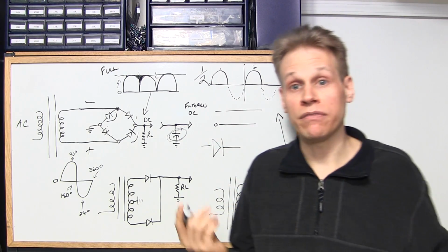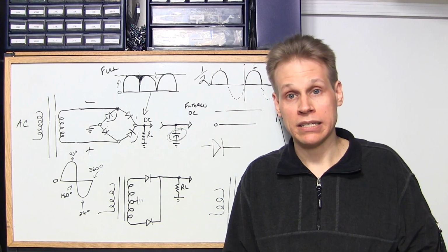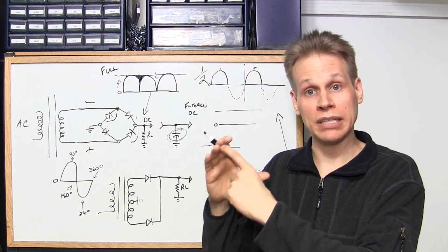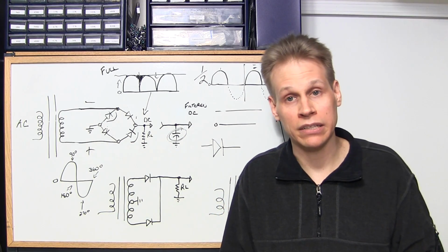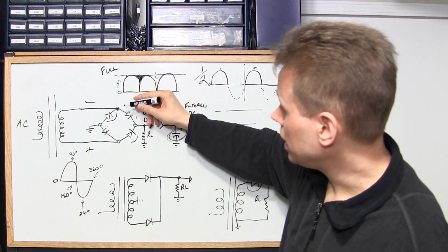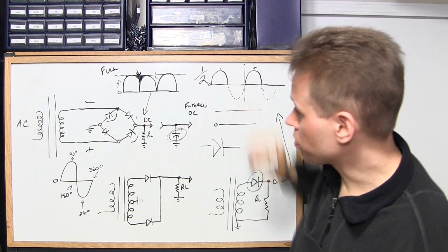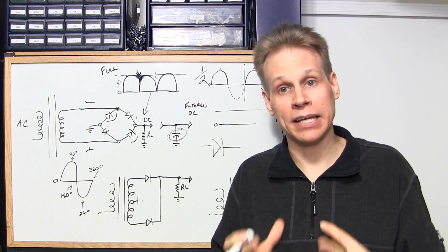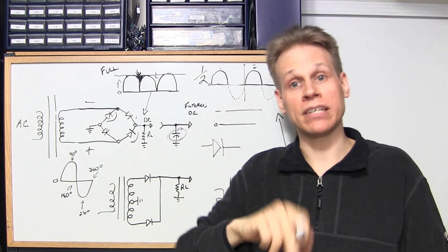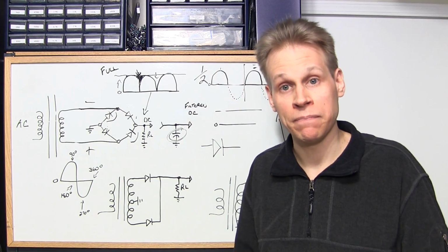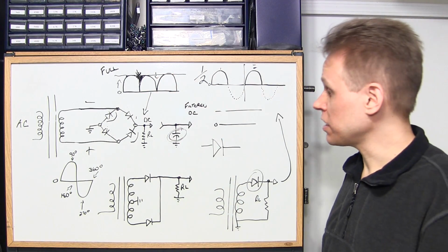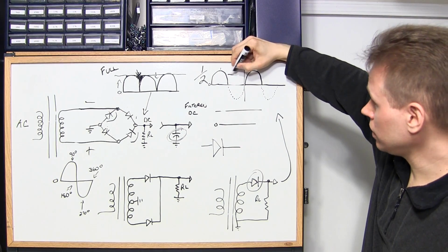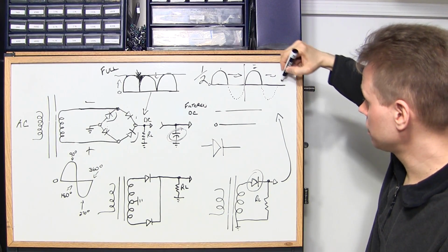So that's why you see in very large linear power supplies, like say a 30 or 40 amp power supply, you've got this really, really big can capacitor inside there. And that's because it needs to hold this area when you're pulling very, very large current. That cap can't drain. It has to act like a battery and hold that up there until the next charge cycle comes again. So this is full wave rectifiers. This is a full wave situation. Now, if you look at a half wave rectifier, look at the distance between these.